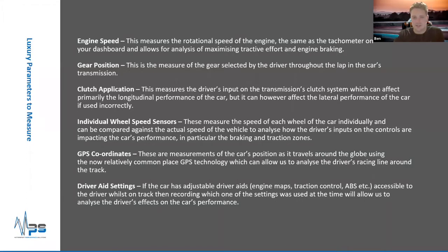If you've got a manual car with a clutch pedal, it's a good idea to track how the driver applies the clutch. Even at touring car level, you won't believe the mistakes that go on there. It's not mistakes, it's that a driver doesn't realize they're doing it. It's very easy to rest your foot on the clutch in high G situations. So that's a good one to watch.